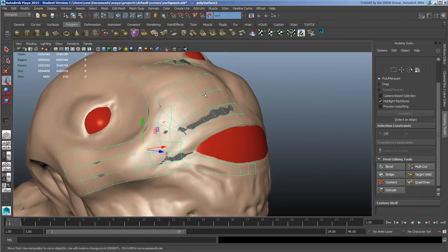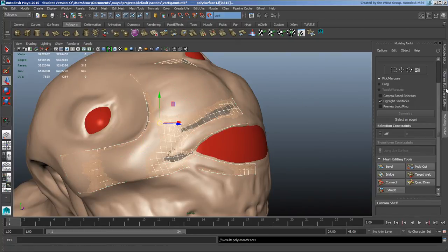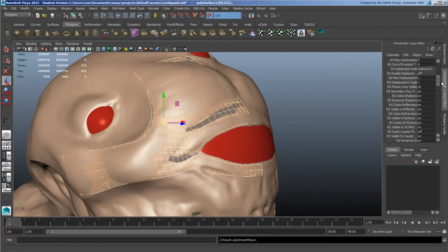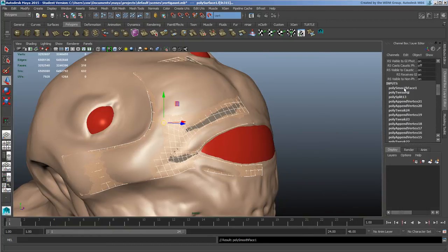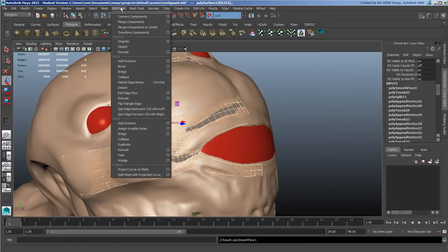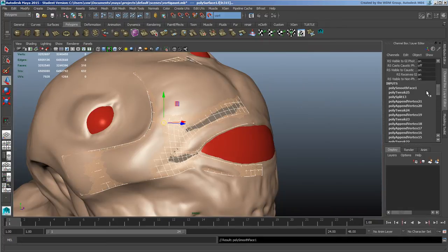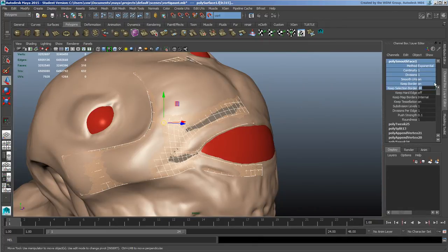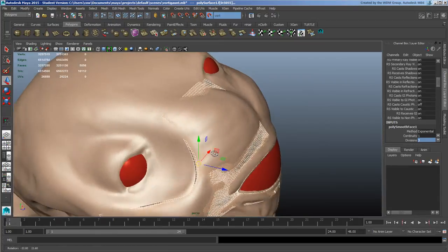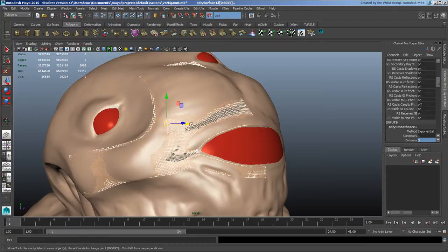and have a look at this. I'm just going to take this mesh smooth feature. It's going to create a mesh smooth face. So again, that's mesh smooth right there. And I'm going to go into divisions. I'll increase that to say 3, which is going to give me a really high res mesh. Lots and lots of points. So many points. What am I going to do with all those points?